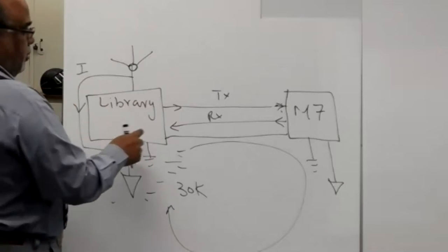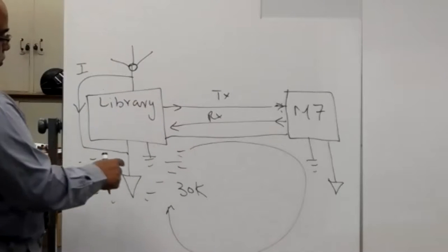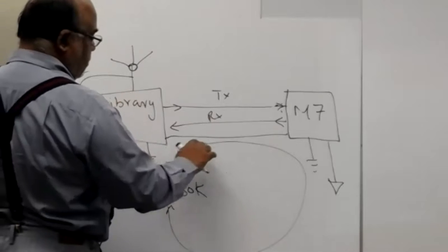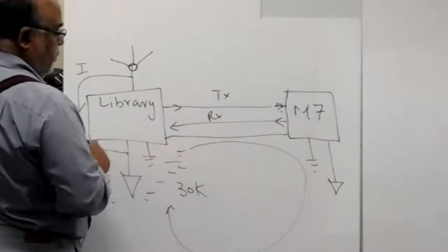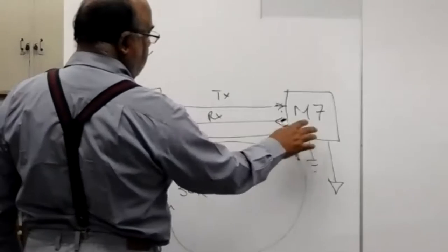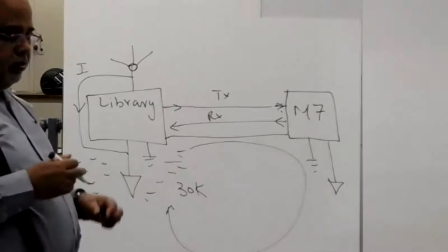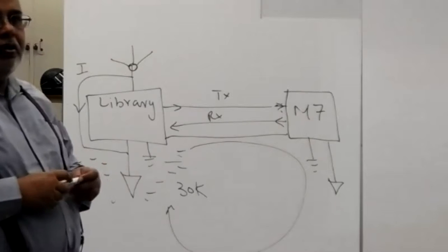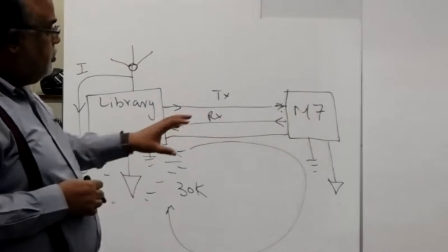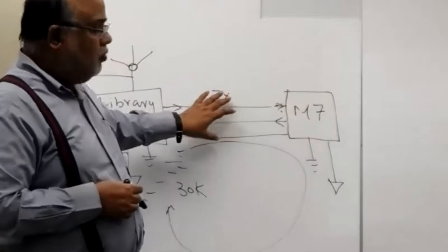Only when it comes to very long distance wires, this problem can occur. Then this lightning can cause another current flow in this direction. So this is such a huge current, I have personally seen the whole of the system go black, burnt, if you have no isolation here.